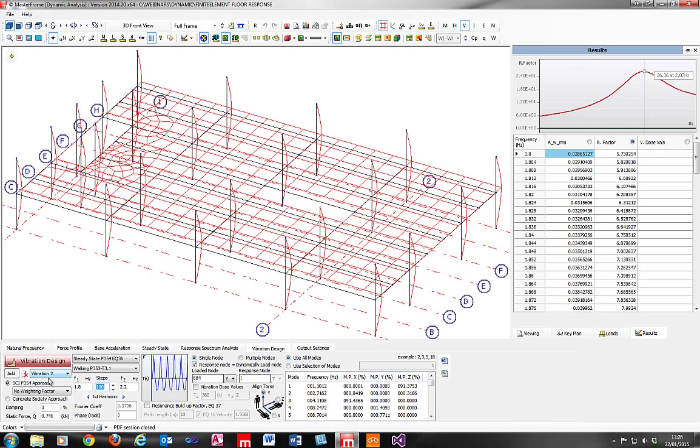So the first case maybe highlights me or zones me in on where is important, and then this is telling me actually what is the behavior at that node over the walking frequency range. Sometimes you get various different peaks here as they interact with the different harmonics, all depending on your actual frequency values that are relevant to that part of the structure.